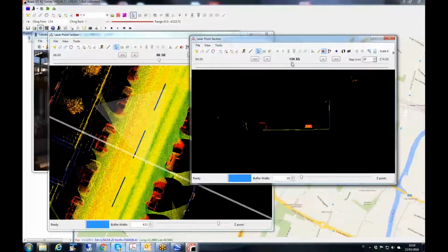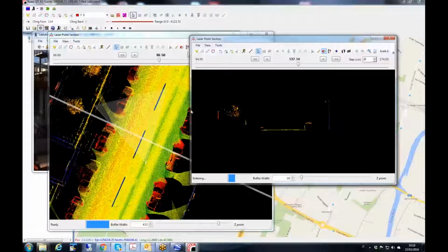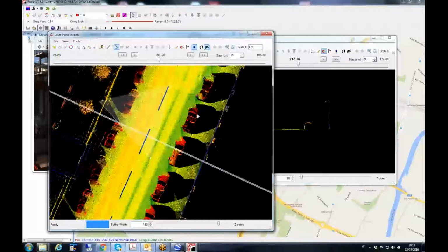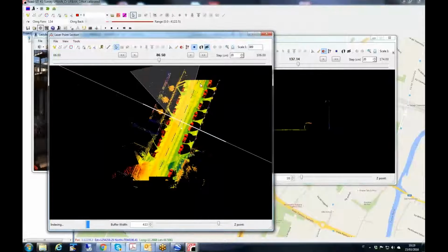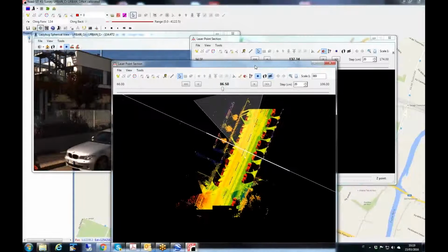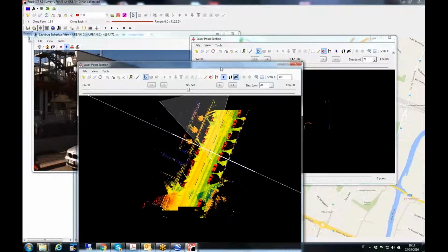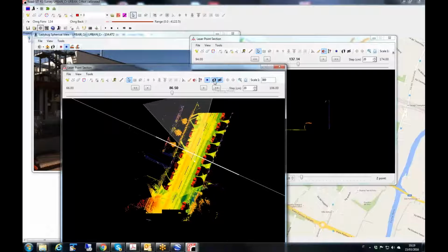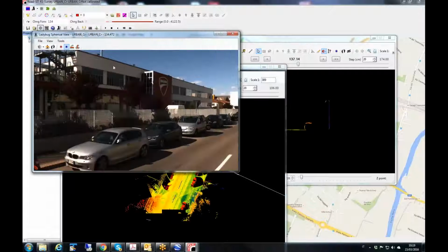So now let me introduce one of the main changes of the section environments, and it's called tracking mode. Okay, these two little feet here. If you enable the tracking mode on the section and on the camera view, when you want to draw something on the section, the camera automatically moves to that part.